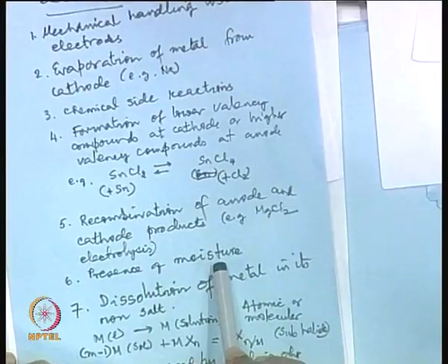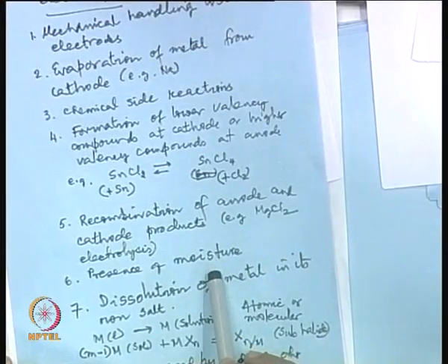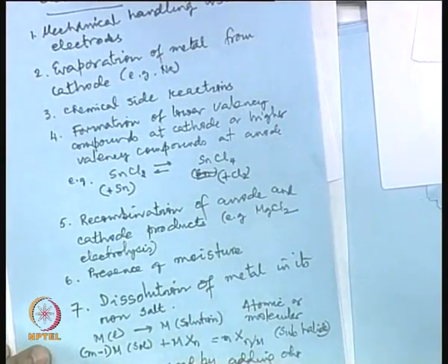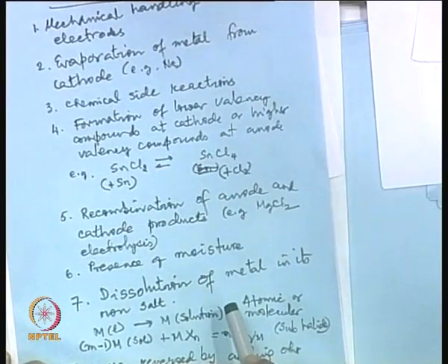If there is moisture in fused salt media, then a lot of current will be lost simply to first remove that moisture. So, we will pass current, but no metal will be deposited. Lastly, in many fused salt baths, a very interesting phenomenon takes place, that the metal is deposited, but the metal redissolves, not completely, but at least partly into the fused salt bath.